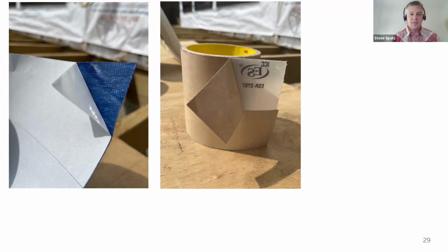So that tape on the left, if you are defining an air barrier that you want to be vapor open, this tape is compatible with the permeability of the substrate that you've used because you want that material to be vapor open and for drying potential to occur through it. Whereas this tape on the right is a vapor barrier tape. So if you are putting that onto a substrate that has similar characteristics, that has either very low or no vapor permeability, that makes sense. But if you are sheathing your walls with CDX because you want a vapor open exterior wall air barrier assembly, you do not want to be using a vapor barrier tape to tape all your field joints of your sheathing.